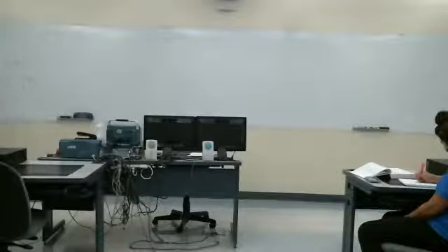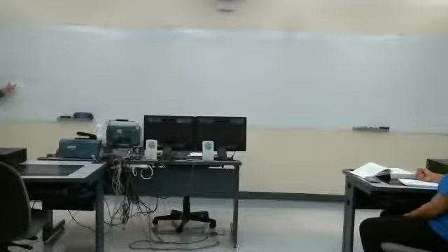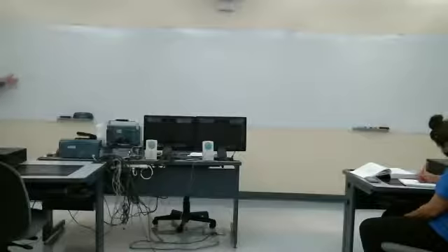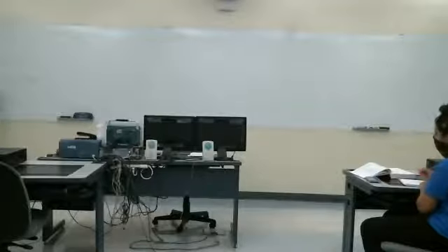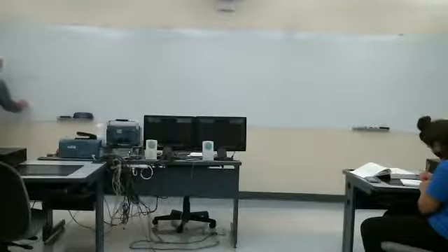That's what this expression says. At t equals 0, e to the 0 is 1, so 1 minus 1 is 0. As t gets larger and larger, this exponential term fades away, and the term in brackets just becomes 1. So this is what y of t, the step response, looks like.